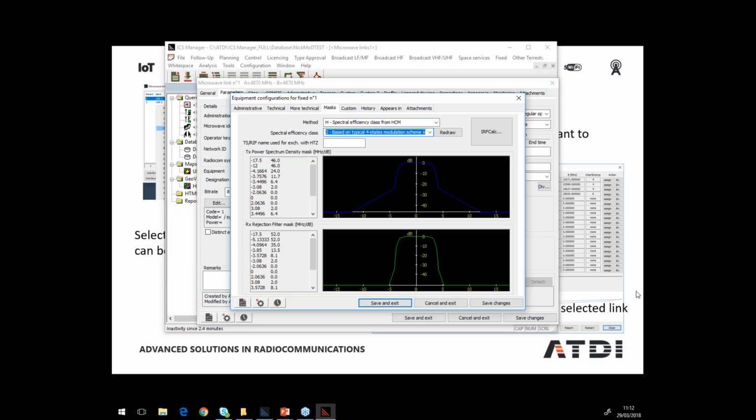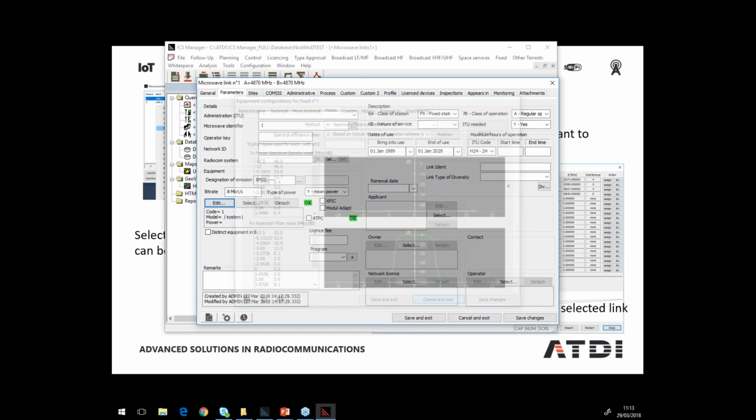What are the critical parameters to fill out for IRF from ETSI setting? Don't quite understand that one. What are the critical parameters to fill out to use for IRF? I think, if my memory is correct, ETSI have got a whole lot of the IRF tables. In other words, a 2G 14 meg bandwidth system versus a 2G 34 meg system. They've got a whole lot of tables published in those, and all the published tables are in ICS Telecom.